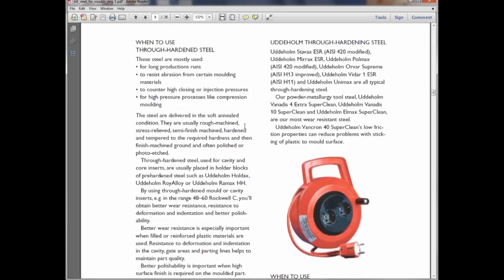when we go for rough machining we leave at least 1 mm of extra material, part stock, for the semi finishing and the finishing. Before we do the stress relieving, we keep extra material for semi finishing, at least 1 mm, because there are many stresses there, so the material can deflect from its original shape. To counter that deflection, we leave at least 1 mm of extra material.